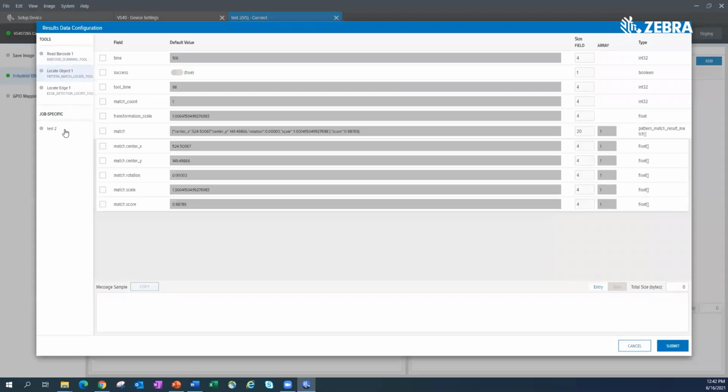On job specific things, if you're using an add-on instruction or similar things for the Siemens PLCs, there is a structure that's going to have a lot of these job specific things built into the header of it already. So a job pass fail bit is one of those that are built into the header that you don't have to necessarily pass as a job specific. That would be additional information that you'd want to pass about the particular job, right?